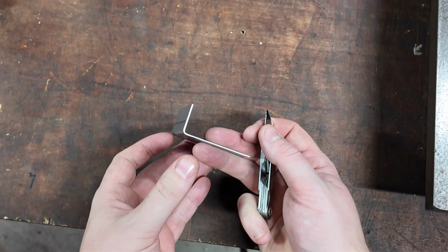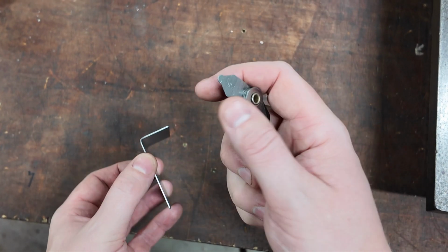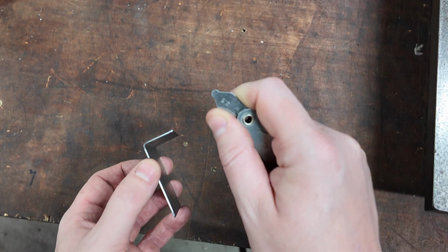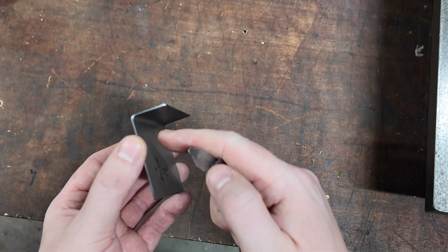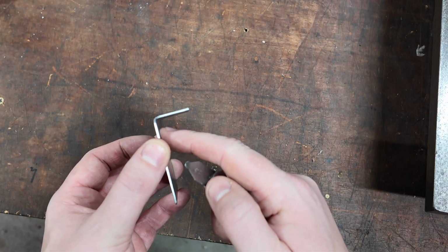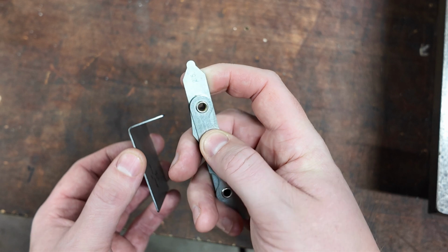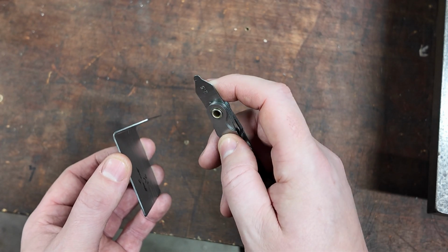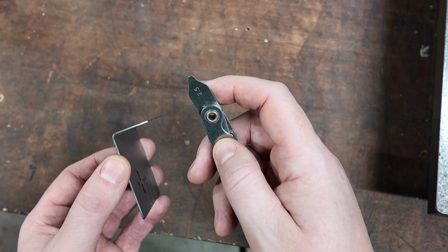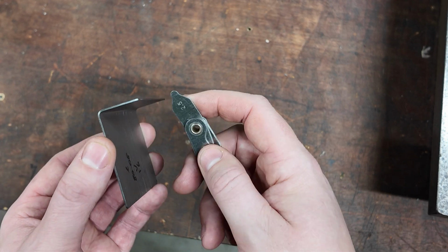Just one point I wanted to illustrate, and the reason for this activity is, so this is a 2.5 millimeter radius gauge, and the V width over 6 formula tells us that the inside radius here should be 2.67, but obviously one doesn't have a continuum of these radius gauges, so 2.5 is the nearest I've got. Is it nearest I've got? Yeah, I think it is. I think the next one's 3.